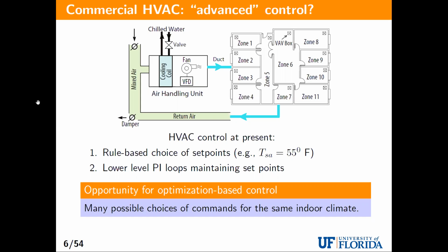This is the kind of air conditioning system you would see in many modern buildings, definitely in hot, humid climates. There's a cooling and dehumidification coil. If you're in Florida, the dehumidification part is not the concern; actually, it's sometimes the opposite, where you need to humidify the air. But in Florida, you need to cool and dehumidify the air, then supply it to the rooms.